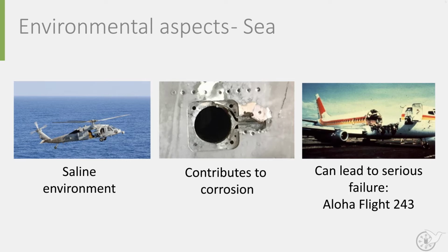Here, the cause was determined to be a combination of fatigue, due to the many short-distance flights, in combination with crevice corrosion caused by the aircraft operating in a coastal environment. Miraculously, only one person aboard this Boeing 737 died, and the aircraft was able to land safely. As a result of the investigation, structural and material design changes were made to the 737.